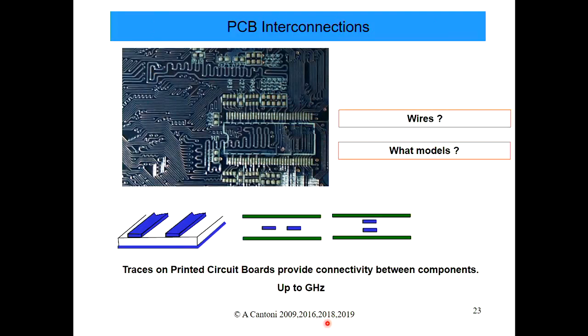The other characteristic that a transmission line has is an impedance, which you mentioned. And that's something else, okay, a characteristic impedance. It's not something you can just measure with an ohm meter, okay? You actually need to infer it. And when you do the lab, you'll see delays and impedance and perhaps get an idea of what they mean.